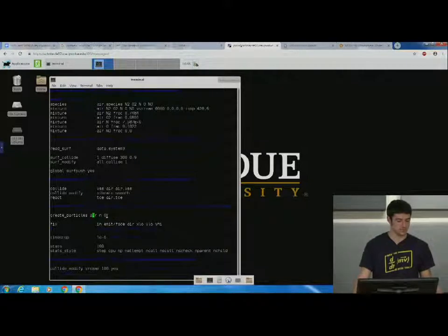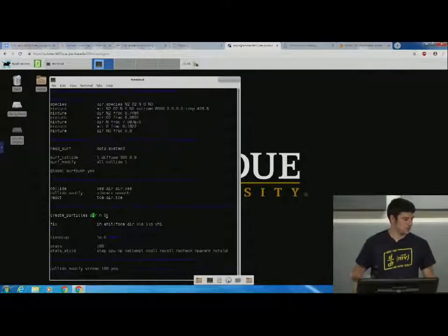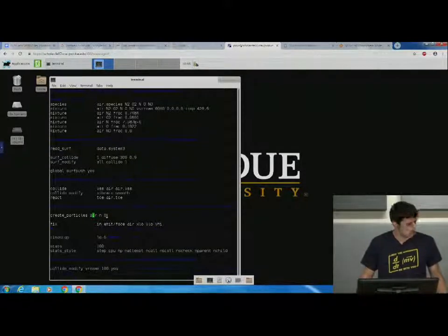Strangely enough, if you put 0 particles, it actually doesn't put in 0. It puts in the number that it would calculate according to your number density, fnum, things like that. So the create particles command is your initial condition at the beginning. This is how I'm populating the particles in the domain. If I don't have that, I don't have any particles in at t equals 0. And if a particle leaves, does a new one appear?